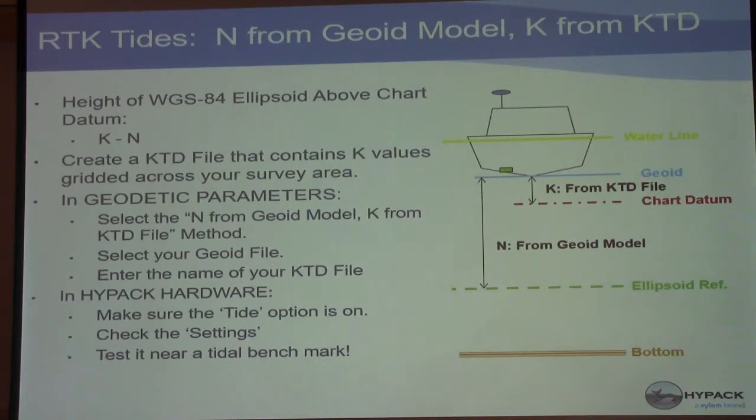It's along the rivers. Are you using a geoid model or any type of... well, I don't think we have the VDatum zones for that area, but there still is most likely a shift between the geoid model and the local datum too. So you're going to have to determine that, or most of that stuff is probably published anyhow, so that could very well be what's going on.